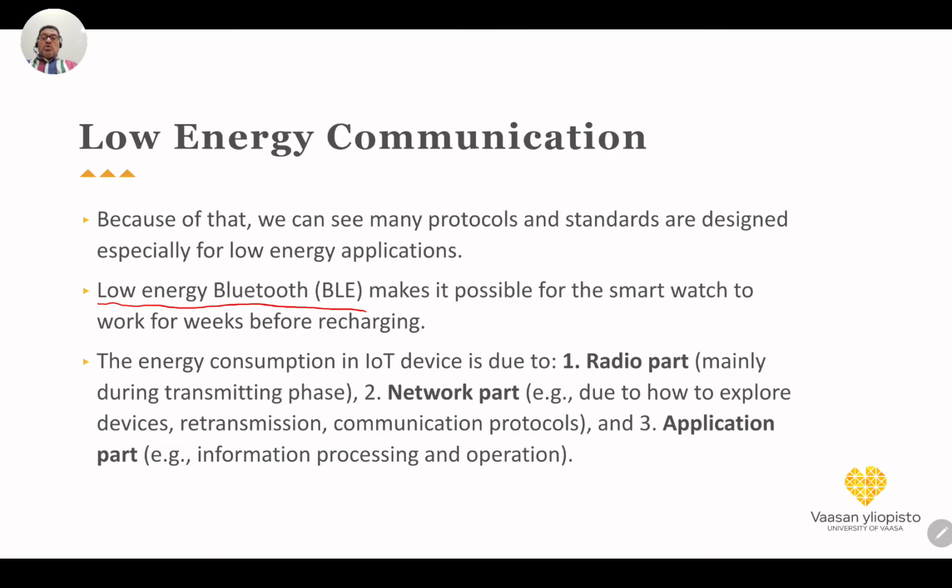The energy consumption in an IoT device is due to three possible reasons. One is the radio part, mainly during the transmission phase. Second is the network part, for example, to explore devices, to send hello signals, and for retransmission, for communication protocols to achieve communication between devices.